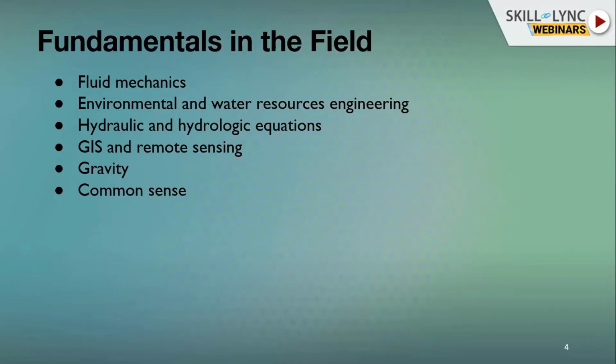When these equations are reduced to 1D or 2D, we call them the St. Venant equations. People should really get to know what these equations are. Other than that, in flood modeling, we come across various structures like bridges, orifices, several weirs, and culverts.